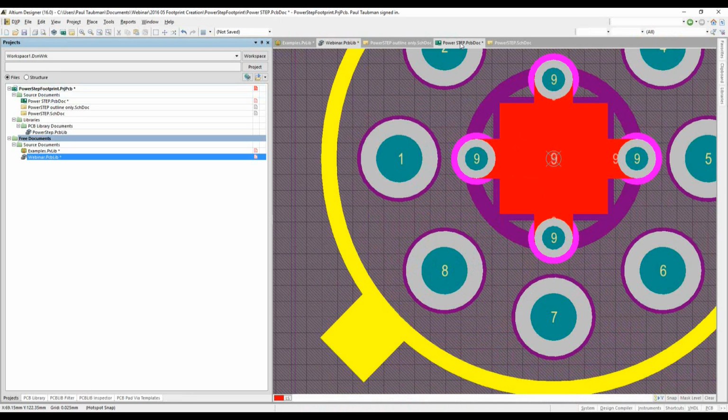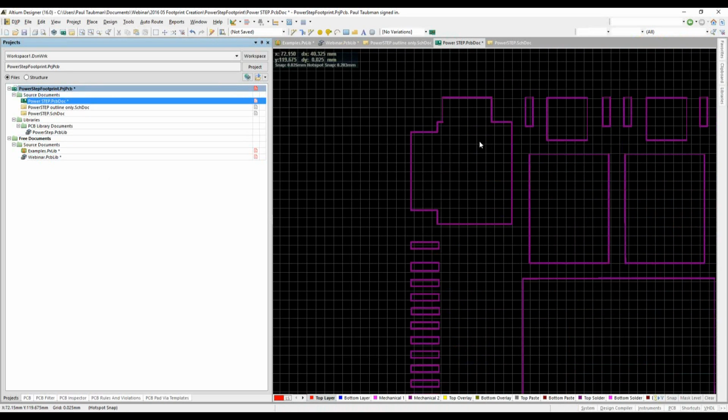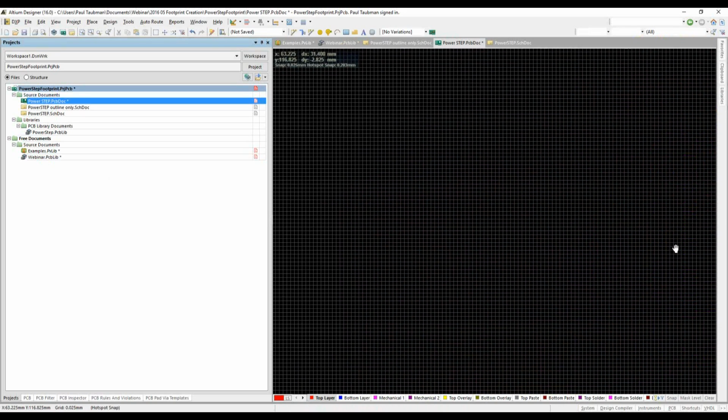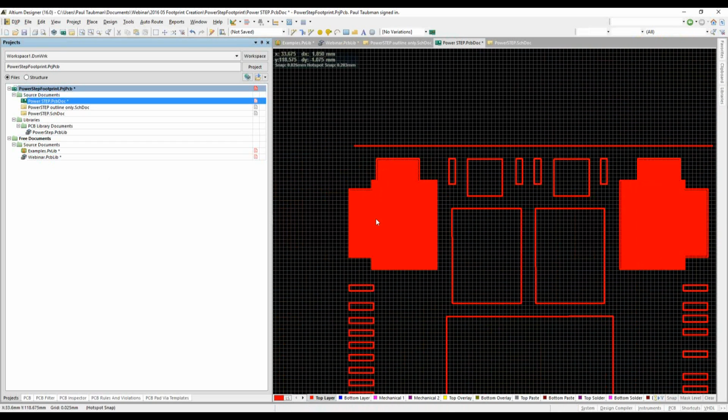Okay, we can do the same thing over here as well. So if we go back over to this, then we can add these pads in, and as long as they're the same name, they'll all work just fine. Now, what if we have something that's a little bit more odd than that? Well, we can do that as well. What we can do is actually do a polygon pour here. So let me delete this polygon pour and just walk through the motions of it.